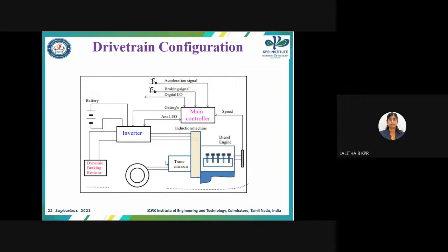The second condition is medium IC engine speed. When the diesel IC engine speed is medium, it can supply sufficient torque to the hybrid drivetrain. Hence, battery recharging control is performed instead of torque assistance control. When the acceleration pedal stroke is below some extent, battery recharging is performed; torque assistance of the induction motor should be achieved to satisfy the driver's acceleration need if the acceleration pedal is pressed beyond that extent. Since the diesel IC engine torque is subject to saturation beyond 80% of the pedal acceleration stroke, the motoring action of the induction motor is made to begin from this point.